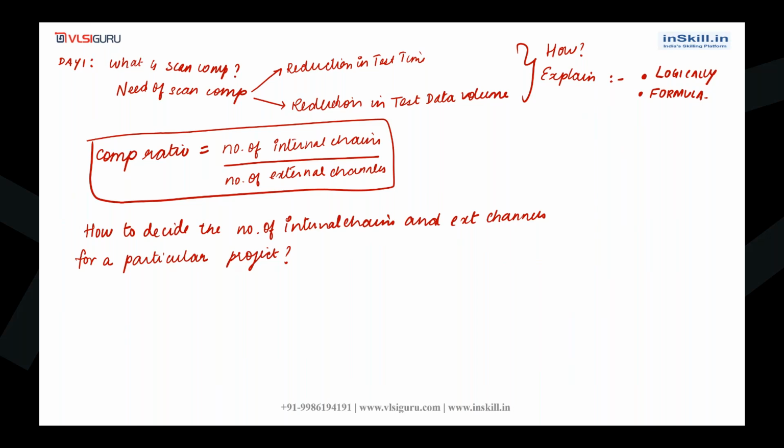Then during the second class of our scan compression topic, in day two, we'll start with the discussion about the EDT logic. As I told, if you are making use of Mentor Graphics tools, then in order to achieve scan compression, you will be adding a logic called EDT logic. So we will try to understand EDT logic. We'll first try to understand the decompressor component.